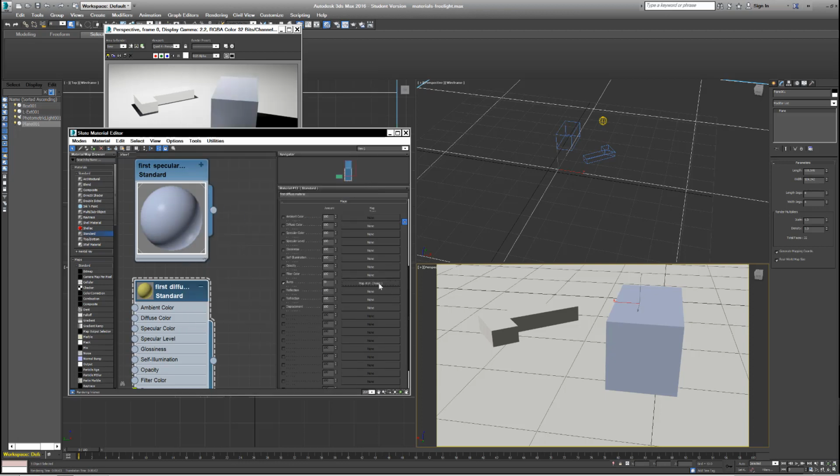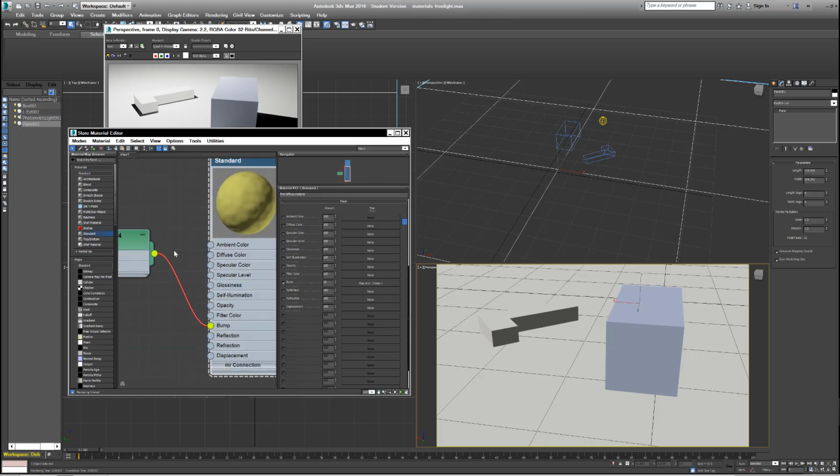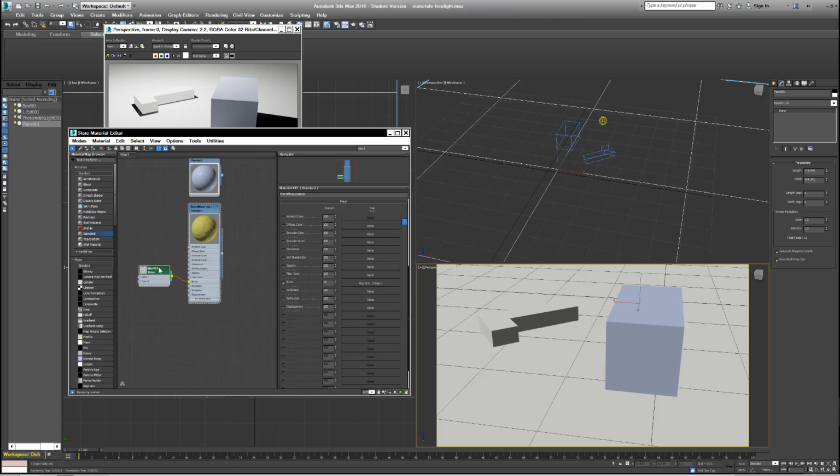It's different from the noise that we animated before. It's simply creating some sort of relief on the surface, some noise that's only going to appear in the rendering. It's not actually going to appear in our viewport. So if I double click this, you see that once I've applied that noise, my surface is bumping, it's becoming dimpled. This noise map that I've just linked has suddenly appeared right here in the bump channel.